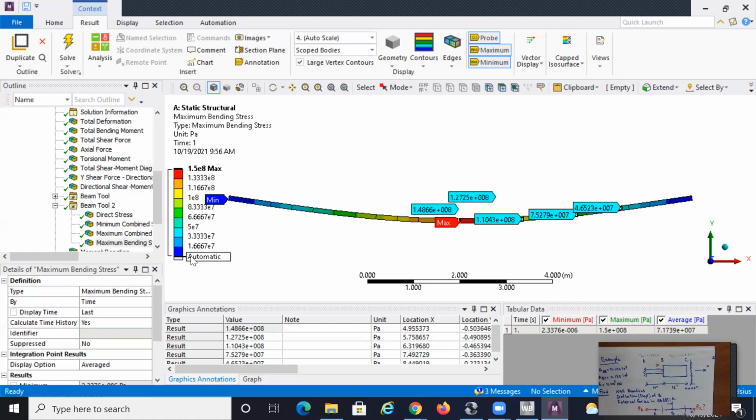We want to go from using beam elements to being able to use the actual 3D CAD or a solid part and discretize it, break it into small pieces. But these pieces are not going to be linear beam elements. They're going to be solid elements. So today I would like to introduce in ANSYS how we work with 3D geometry and solid elements and still be able to get the same results that we have obtained in the past.